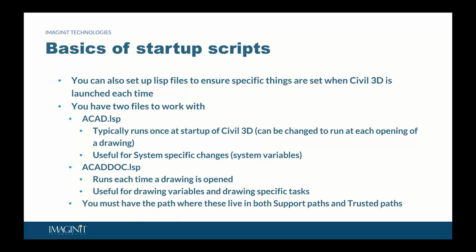The acad.doc.lsp runs every time a drawing is opened, and it's useful when you have drawing variables or drawing-specific tasks that need to be included. And again, you must have the path where these live in both support paths and trusted paths in order for these to run correctly. I'm not going to go into the details of what I put in mine, but I have an ACAD.Lisp that I set up a specific way and an ACAD doc that I have set up a specific way.